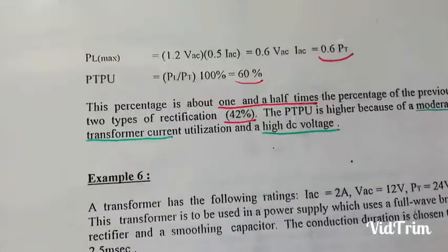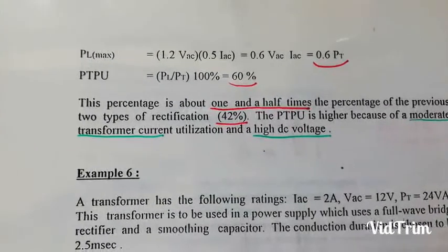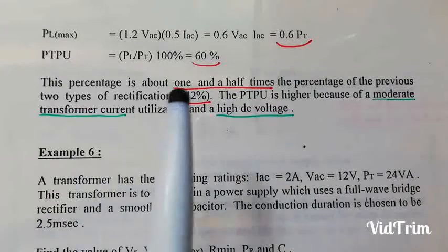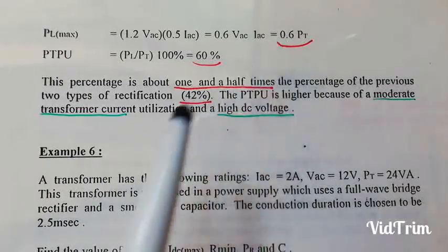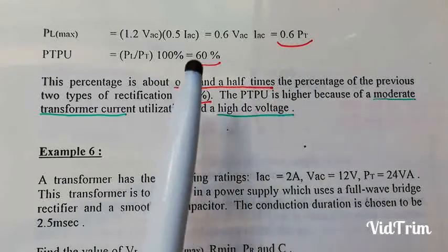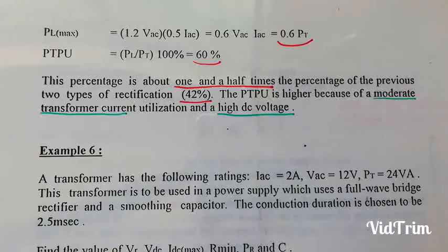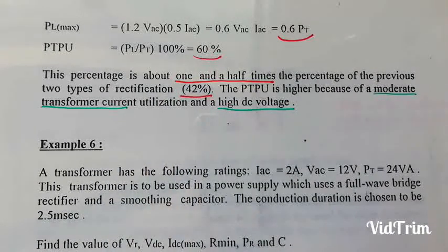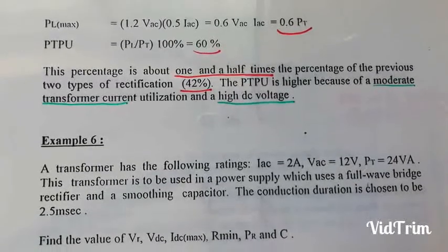Now here's the conclusion. When we used a cap, we were able to get only 60% of the capacity of our transformer. That's the idea. 60%. Can't get more than that. Now, if you still remember, when the cap was not included, we got 100%. We altered the shape of the current. Now we get only 60% of our transformer. So that tells you what kind of transformer you should buy for your application based on this.